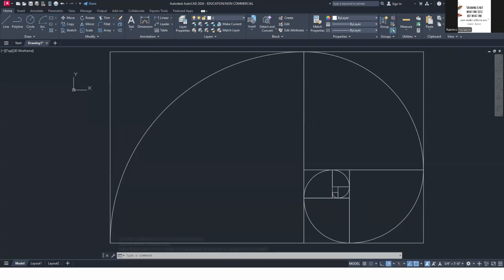So choose the option center, because we know the center. And then it asks for the endpoint. That's when you just click the endpoint. Do you want me to repeat that? Okay, it's not difficult. Let's do that again. Let's delete this. Try it again. It's faster the second, third, fourth time around.